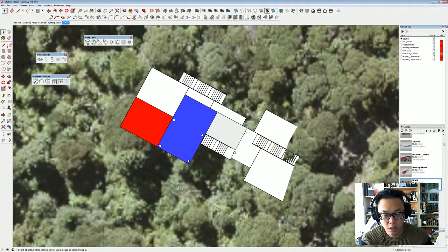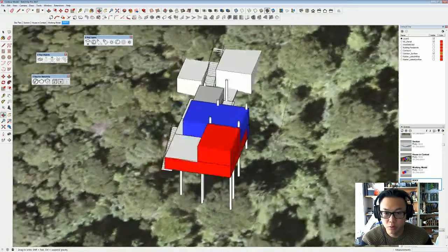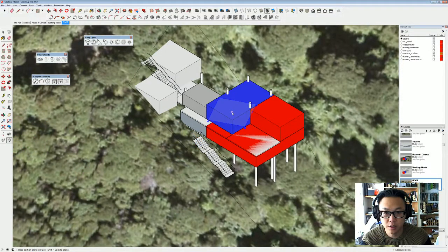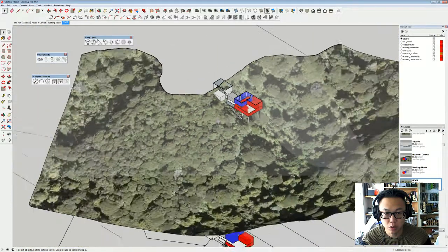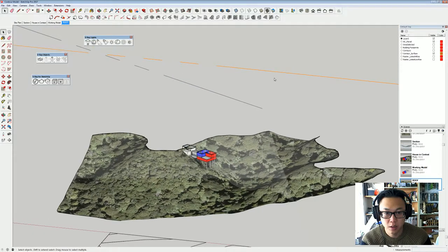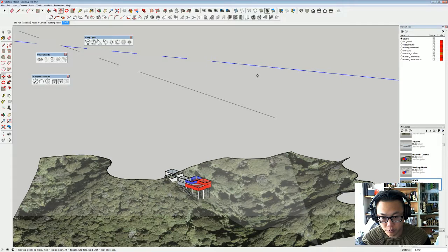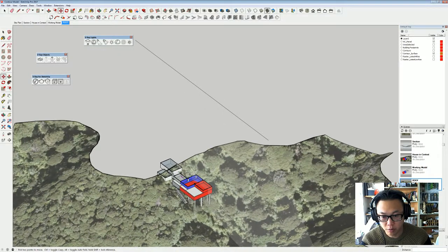Roof. And then actually, if we want to do floor plans, we have to use the section tool. So it's this one here, section tool, and then you just make sure it's stuck on the plane that's parallel to the floor. So you click once, then you zoom back, select it, and make sure that it cuts all the spaces that you want to design. So here we cut through the lobby, kitchen, dining, and the living area.